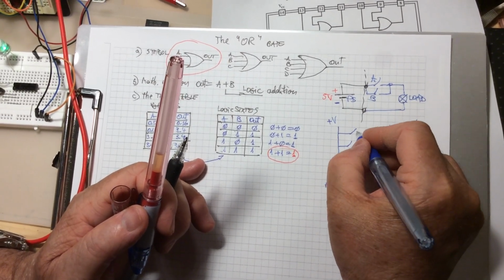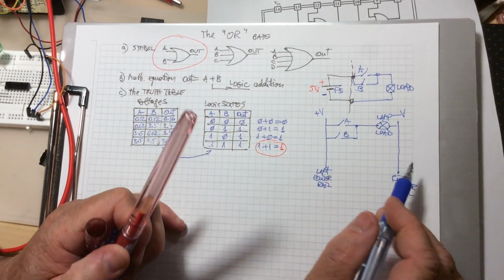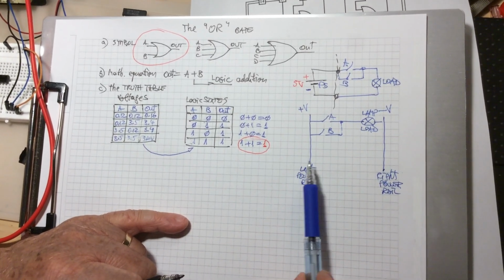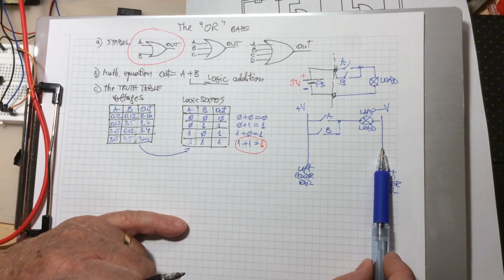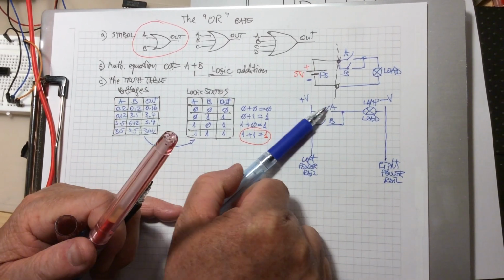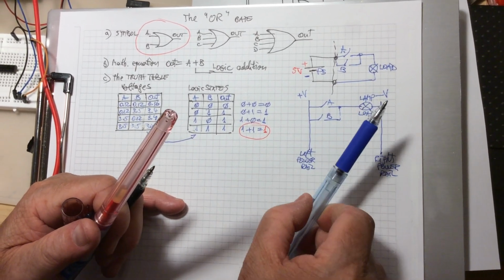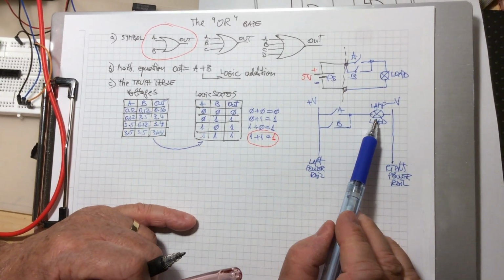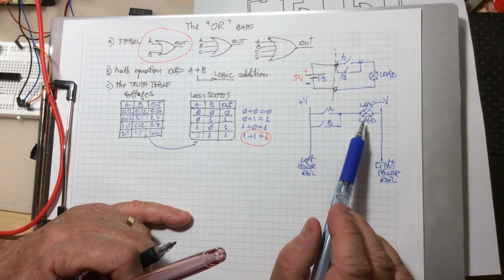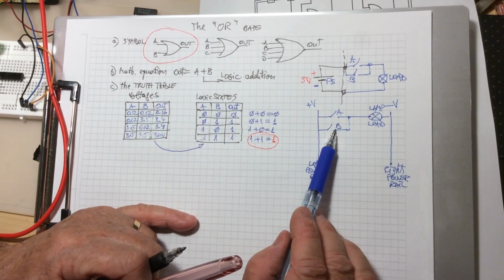This is the switch A, and this is the switch B. So here, in this diagram, the purpose for any diagram connected between the positive and the negative of the power supply is that by having some control elements here on the left, to be able to energize the output, because the purpose is to control your load. If it is a lamp, it's just to put the lamp on. So in order to have energy over that lamp here, what do you have to do? You have to put on either the switch A or the switch B.